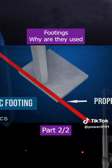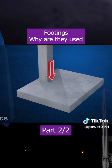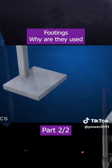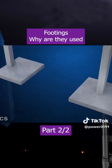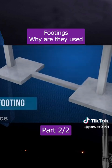This footing can carry a considerable amount of load on the structure. However, if the load increases beyond a certain limit, the structure may fail. The trick to solving this problem is transferring the excess loading into another adjacent footing with good strength. This transfer is accomplished by placing a connecting beam in between, which acts as a strap.